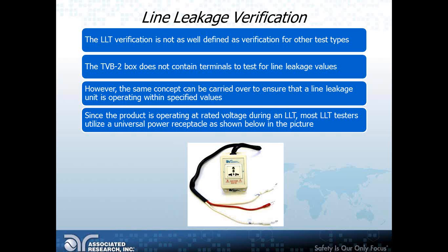Basically we can utilize simple resistors and place them between ground and line, to see if the leakage tester is measuring the correct leakage. Since the leakage meter reads between ground and neutral for normal polarity and ground and line under reverse polarity, separate resistor values can be wired between line to ground and neutral to ground.